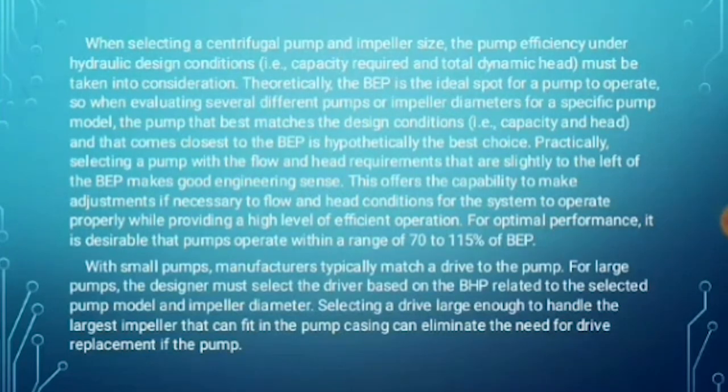With small pumps, manufacturers typically match a drive to the pump. For a large pump, the designer must select the driver based on BHP related to the selected pump model and impeller diameter. Selecting a drive large enough to handle the largest impeller that can fit in the pump casing can eliminate the need for drive replacement if the pump is upgraded.